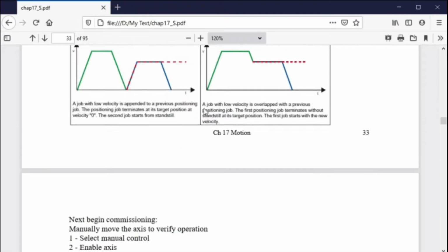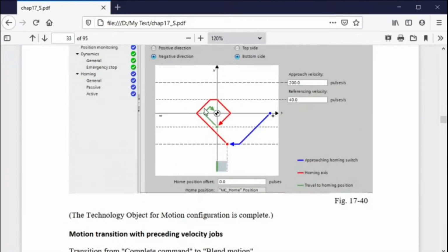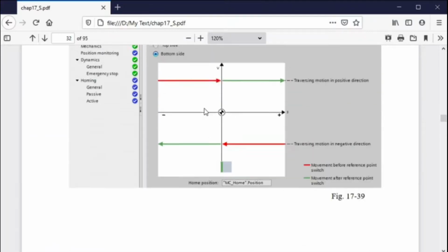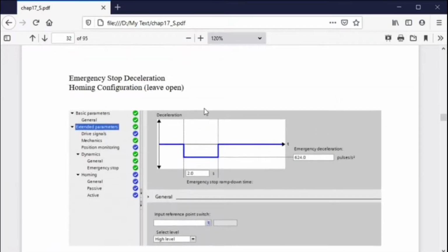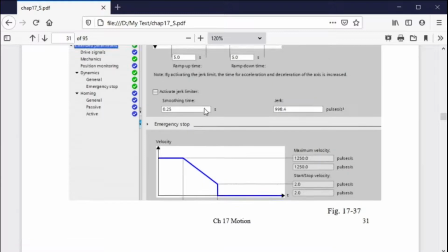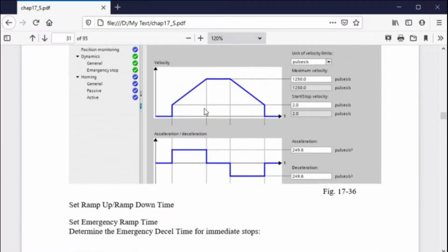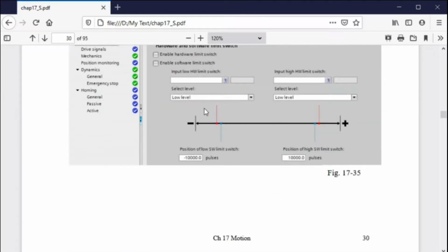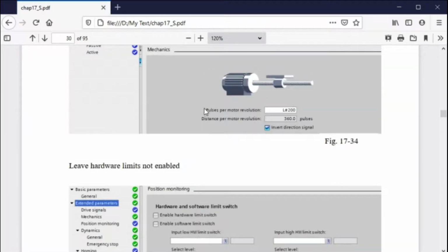The thing I'm looking for here is the number of pulses that you need to go one time around. I believe that's one of the variables that is entered in here, and I'm going to find it in a second, hopefully. So for the Siemens, if you pulse it 360 times, it should go around one revolution.